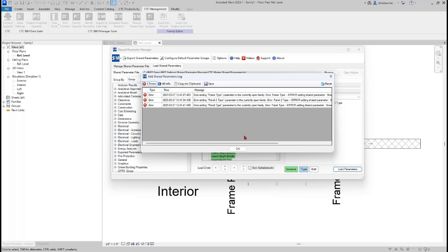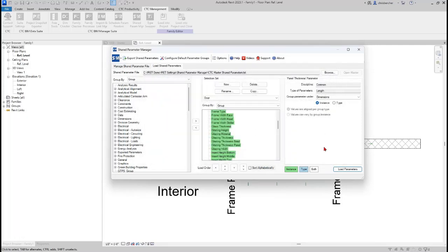And I'm going to get the same issue with them all because it's the panel. Same problem. I've got to have a door panel loaded in to go ahead and make sure that those two parameters work. So that's what these errors stand for. But now I know, I forgot to do something prior to this, or my door template that I'm trying to start from wasn't defined properly. So that's on me for not remembering to load those two pieces in first.